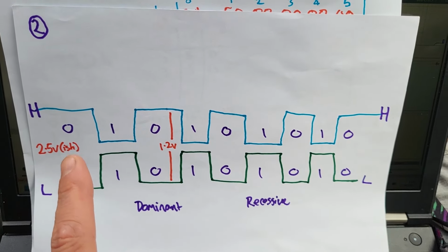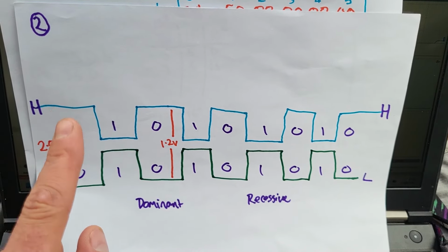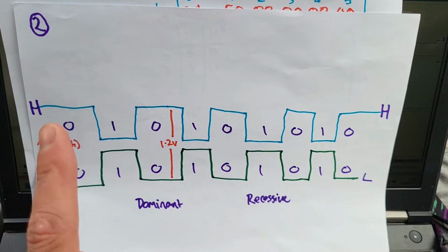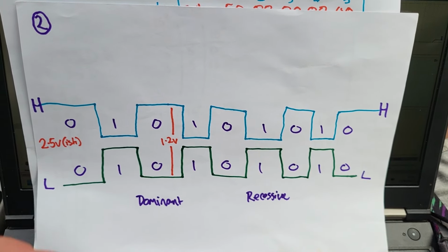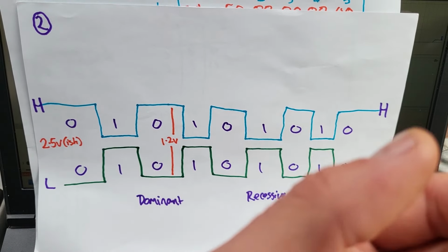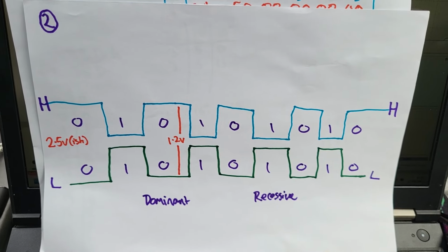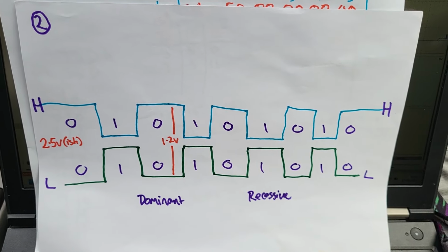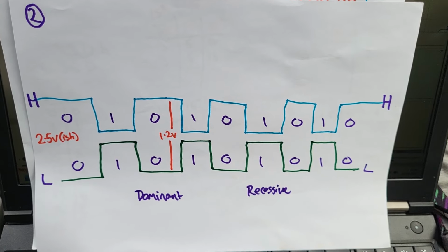One thing which is quite important with CAN bus is that we always connect, so if I've got a device on this side and a device on that side, we always connect high to high and low to low. If it was serial, you might have T and R, transmit and receive, and then on the other end, you'd have the opposite. But CAN bus, it's always got to be like this. So that's roughly what the waveform would look like if we were to scope it.